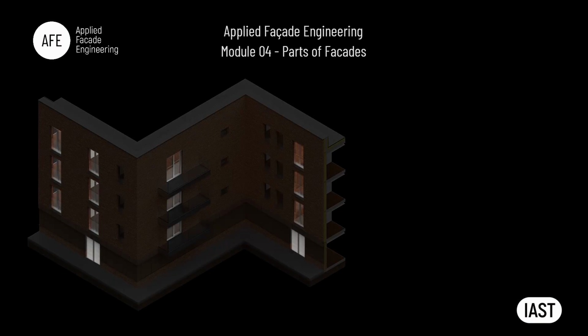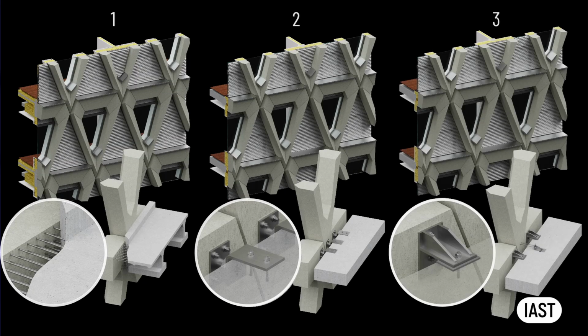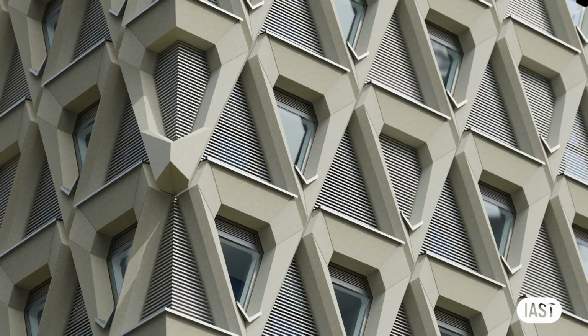The facade assembly options presented in this course provide a great opportunity to talk about windows, doors, balconies, and ventilation outlets. In all three options where the precast concrete is the performance facade, windows are placed within the triangular or diamond-shaped apertures of the precast concrete screen. For obvious reasons, placing openable windows within non-orthogonal apertures is a challenge, as it will require bespoke ironmongery.